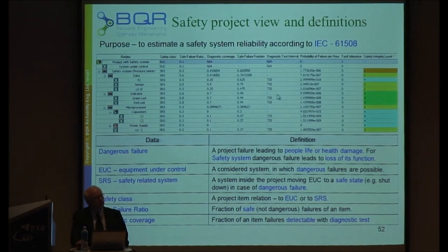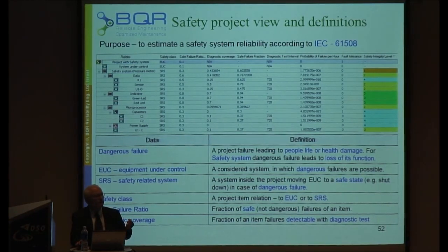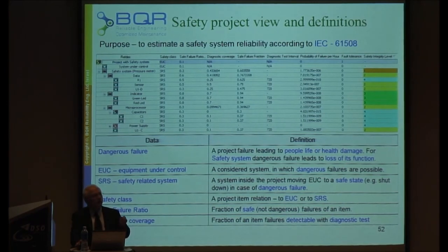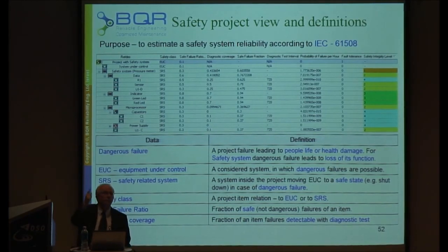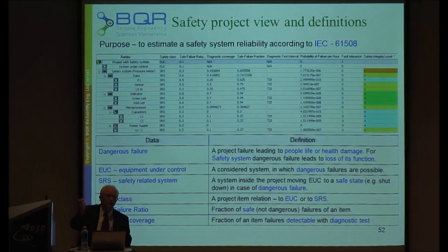So only to give you an understanding of what happens with those fire alarms, there should be a procedure from the building maintenance that they should come once a year with a special utility with smoke, and they should work to see that it's working. And if some of these are not working, they need to replace them.